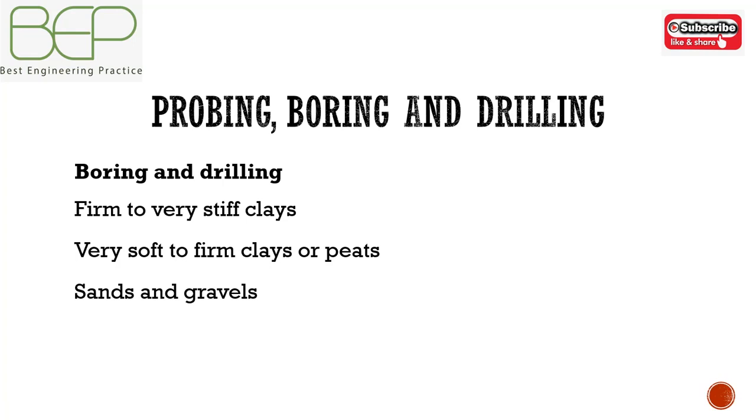Sand and gravels. Standard penetration tests (SPT) are carried out at 1 to 1.5 meter centers. Small disturbed samples are recovered from the SPT split spoon in sand. In sands and gravels, large disturbed samples are taken at 1 meter centers between SPT tests.